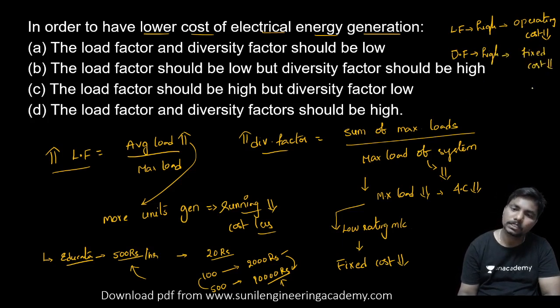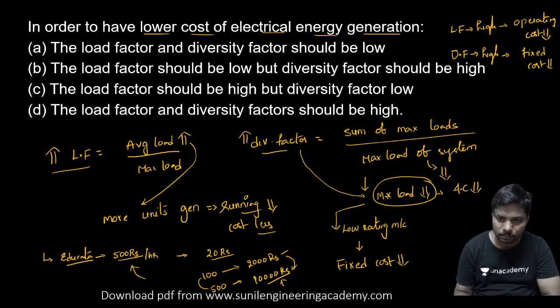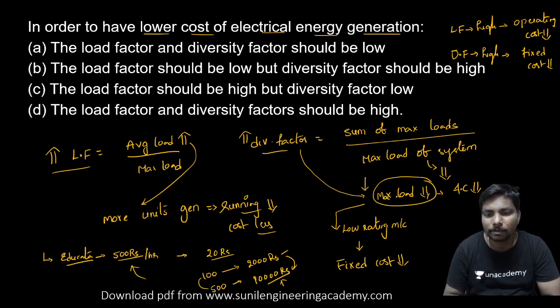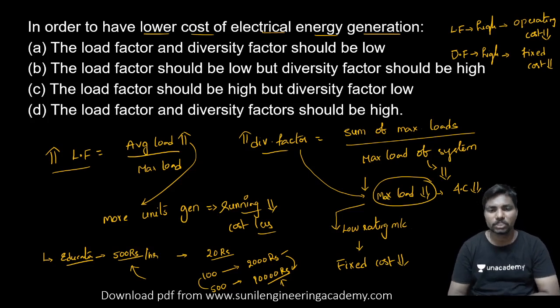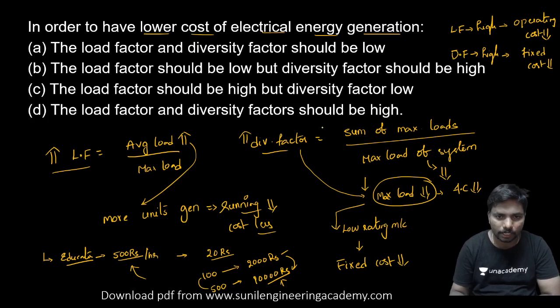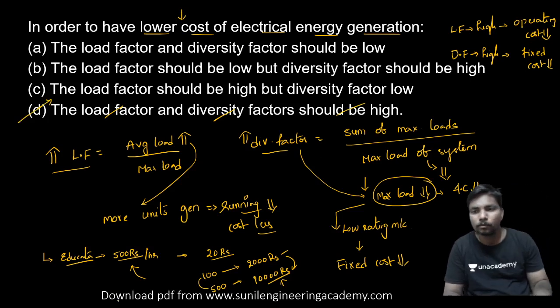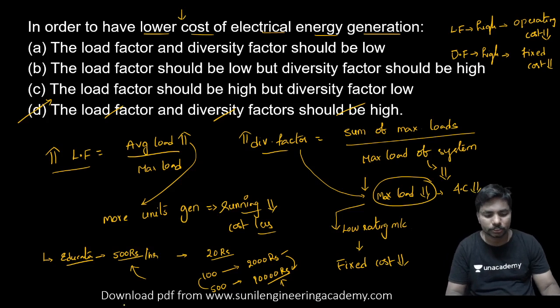This diversity factor is used to find out the maximum load of the system. If both are higher, both costs are low. So to get the lower cost, load factor and diversity factor should be high.